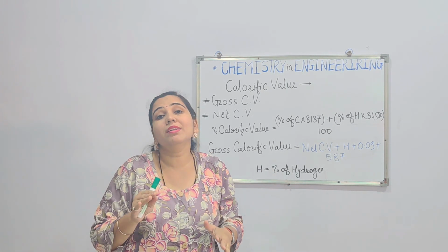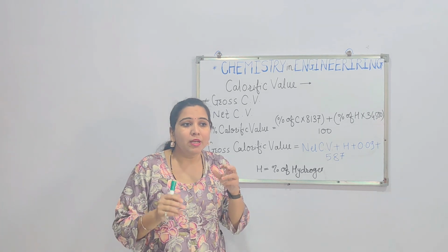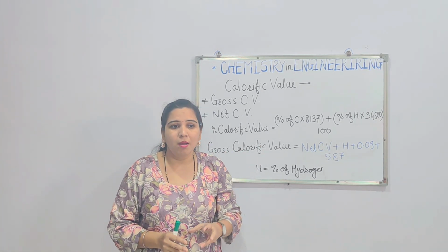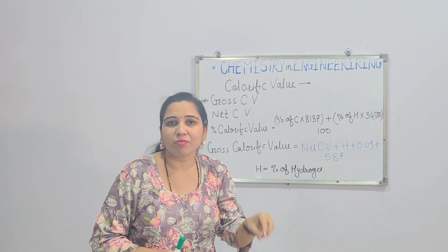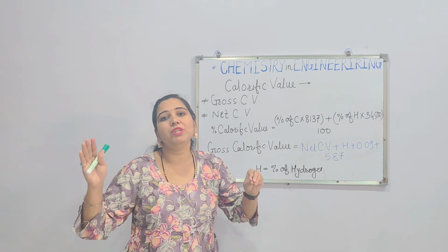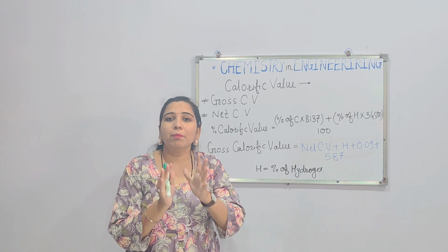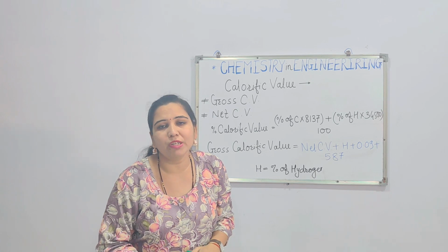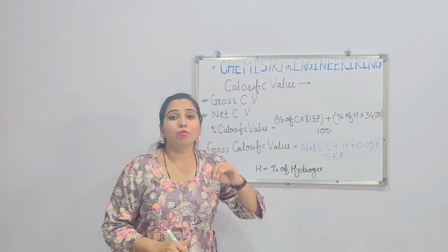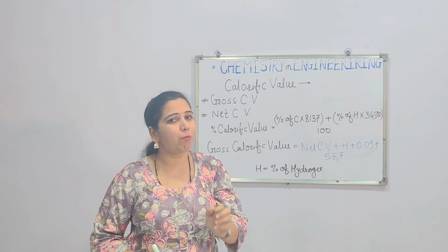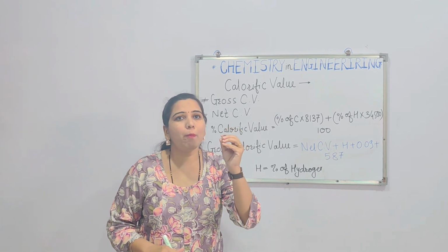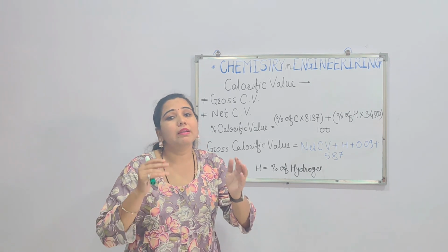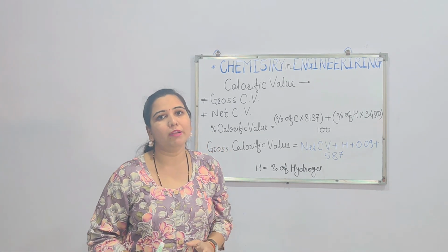We have to compare different types of fuels or samples of coal from different mines. Even if the sample is the same coal, if it is from a different mine, it will have somewhat different properties and different percentages of its components. So for getting the proper quality of fuel, the proper price of fuel, and the required utilization of the fuel, there is a need to study calorific value.